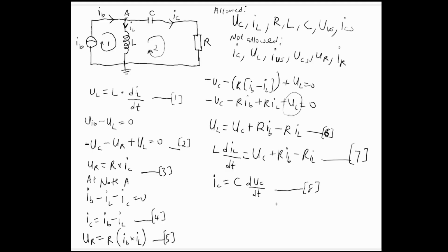What do we do with it? We try to find structural equations that we can use to manipulate for the left hand side. So we have IC. Let us go back to the circuit. Where is the capacitor in question? This is the capacitor in question, right? Good. Because we have IC, we can make use of KCL, Kirchhoff's current law.